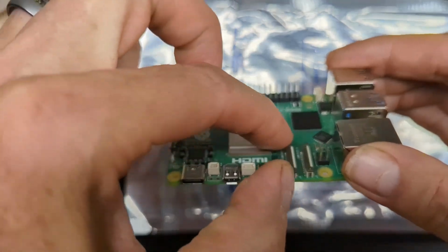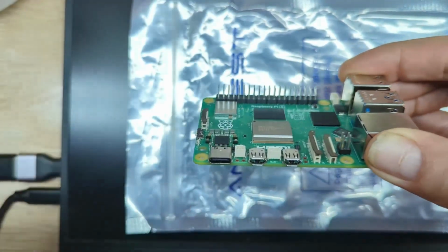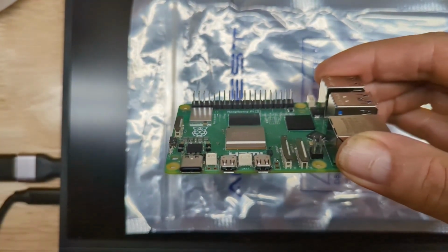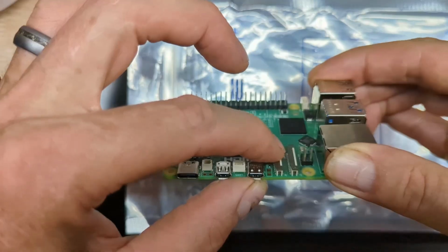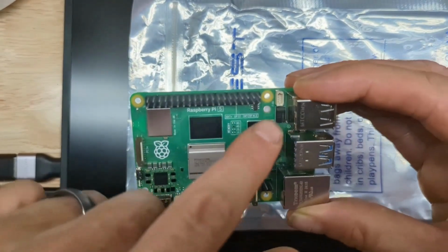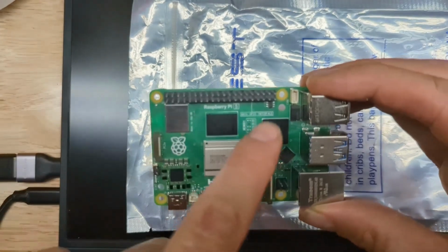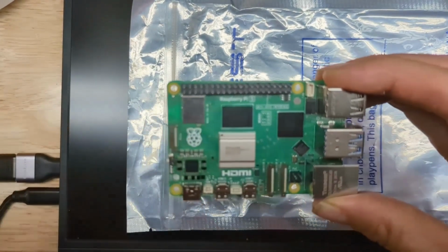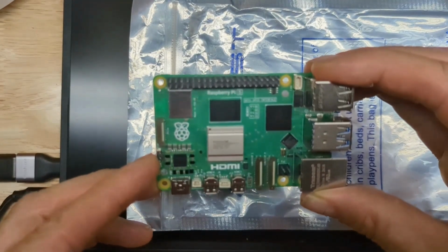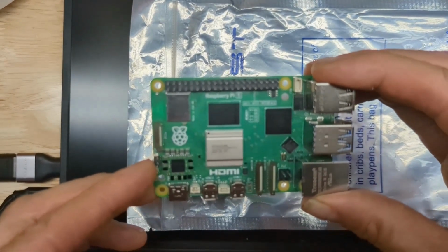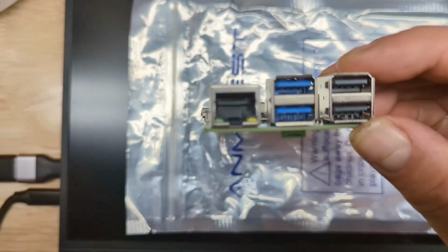Now, these little ribbon connectors, this is where your Pi Cam HQ with a ribbon connector would slide into. Basically, the ribbon would fit down into the slot, and you would push the little tab down to lock it into place to keep the ribbon from disconnecting. And this little white port, this is your power port for the onboard fan. Row of pins is your I/O ports. This allows you to control different sensors like humidity, temperature. You could also control on-off switches for different fans, things like that. And then on the end, we have an RJ45, your standard network cable connection.